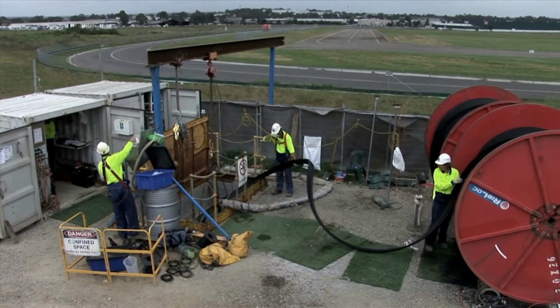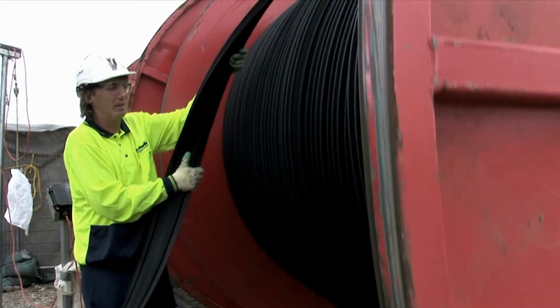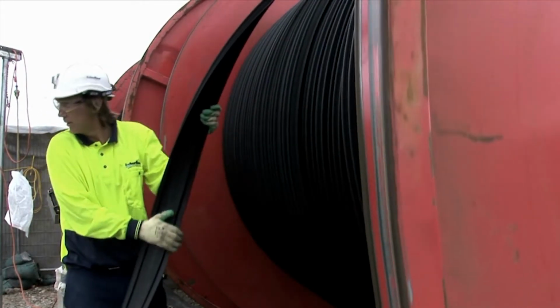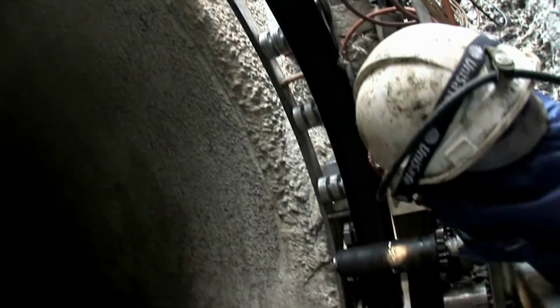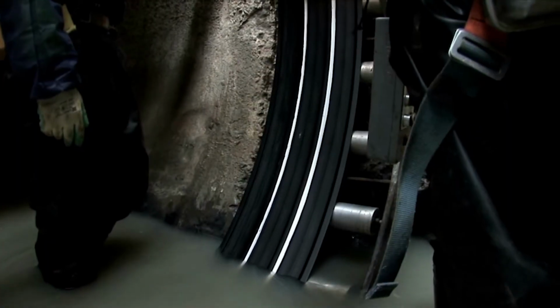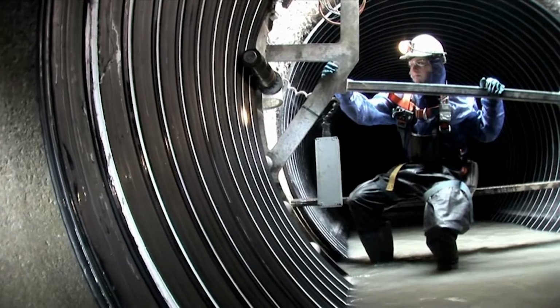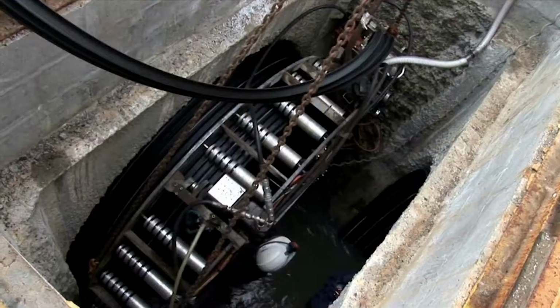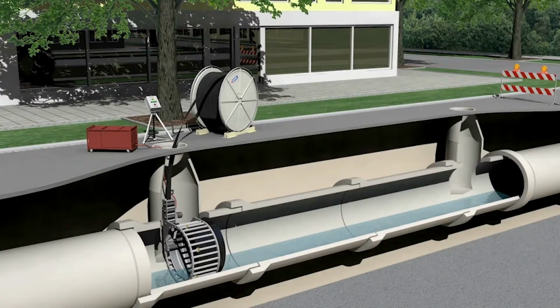The plastic profile that forms the liner is reinforced with steel that's completely encapsulated within the HDPE material. The steel reinforcement is selected to provide a liner with sufficient stiffness to meet the design requirements of the project. The SPRPE winding machine is positioned in the host pipe and winds the profile to form a new pipe with a fixed diameter.